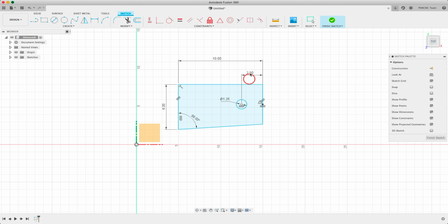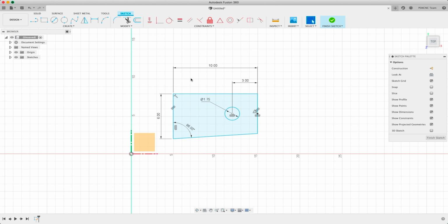So now any of these things are totally changeable if we didn't like how they got set up. This could be 1.75 inches. We could change this to be 3 inches. What's really great is we can say I want this one. So I've got it selected. I've double clicked on it and I click up here. It's going to take the dimension D22, the representation, and I say divide by 2.